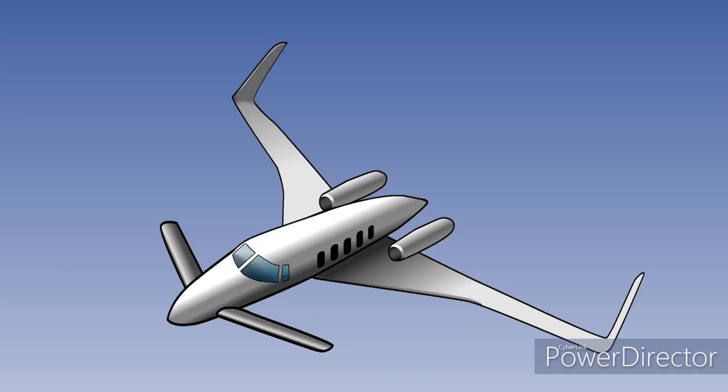But if the foreplane stalls first, then control will be lost, and the maximum value of CL is reduced, since both foreplane and main plane are lifting surfaces. In the next lesson in this series on stalling, we return to conventional aircraft and the topic of spinning.